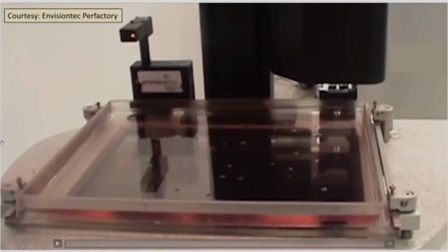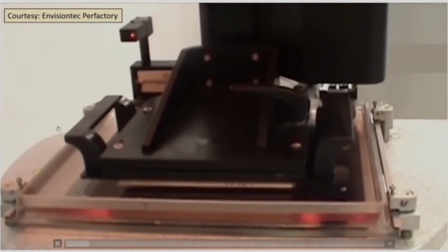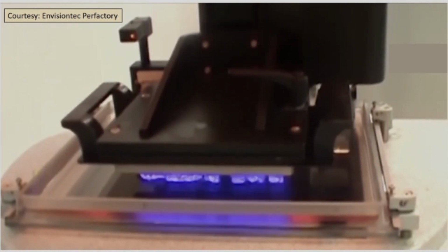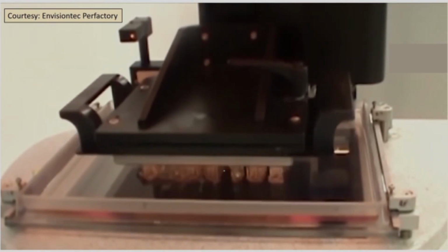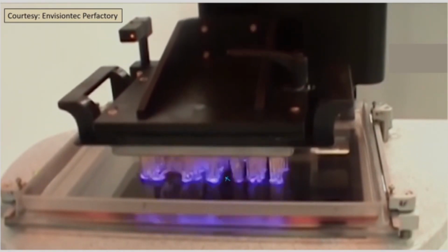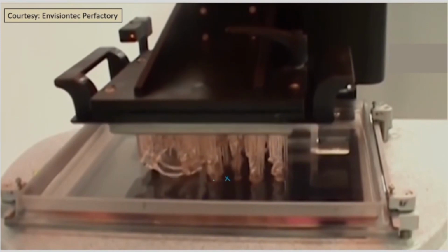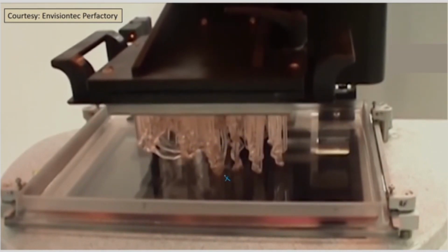This video will show you the conventional process developed by Envision Tech. Here you can see the thing which just came down is the build platform, and from the bottom UV light is coming. You can see that the part is stuck to this build platform and hanging upside down. Also, it can be noticed in these regions there is no light coming because there is no material here. The light is falling only on the region where there is a material. And as the process goes on, the part keeps moving upside and the layer gets cured on the bottom.